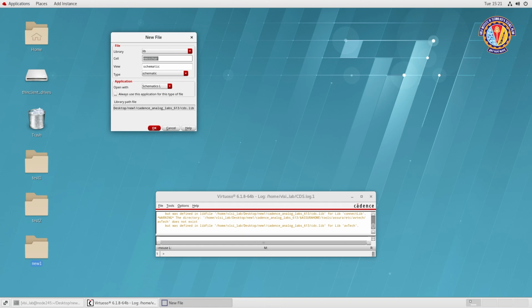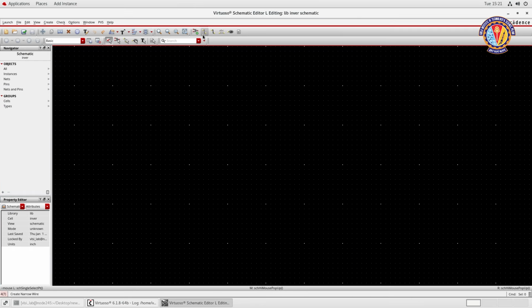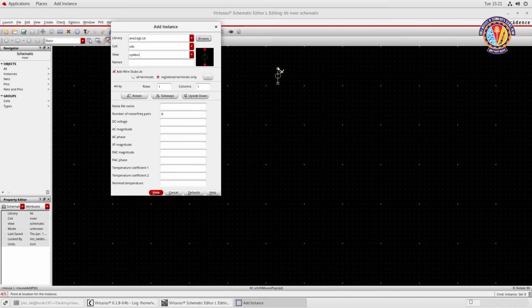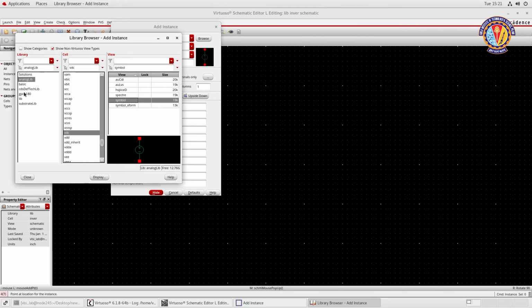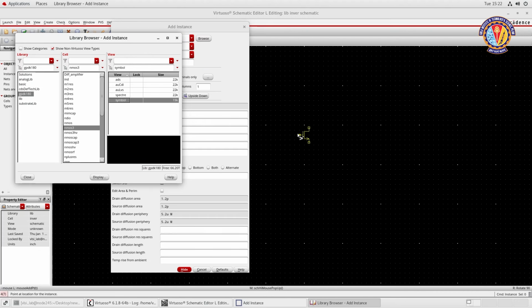Now we are going for the transient analysis of a CMOS inverter. Fine. We will give the name as INVER. Okay, inverter, inside the same library. Okay. Last time when we were creating the NMOS design, we just used only one transistor. But as it is an inverter, we need both NMOS as well as PMOS. So first we'll go to GPDK 180, follow the same process. So there's an NMOS 3, we'll click that, we'll place the NMOS here.